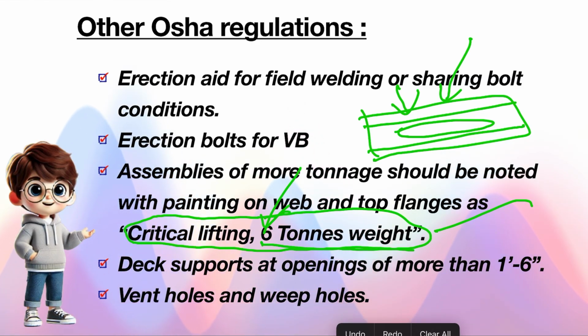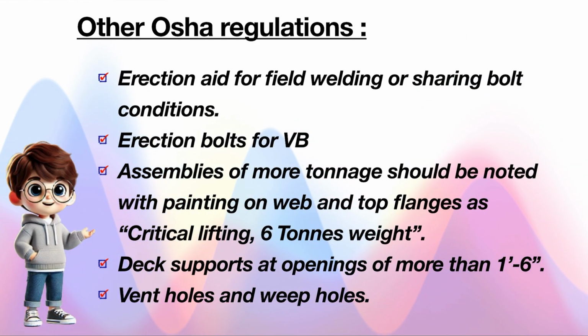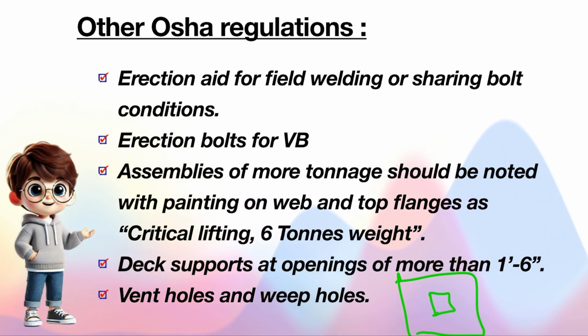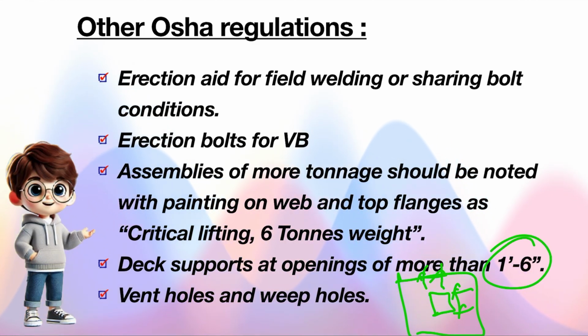And now after installing the complete deck, for example for plumbing purposes or to install RTU frames or something, if you cut some portion of the deck to form an opening, and if that opening size is crossing 1 foot 6 inches, we need to make sure that there is structural framing which will support those deck edges.